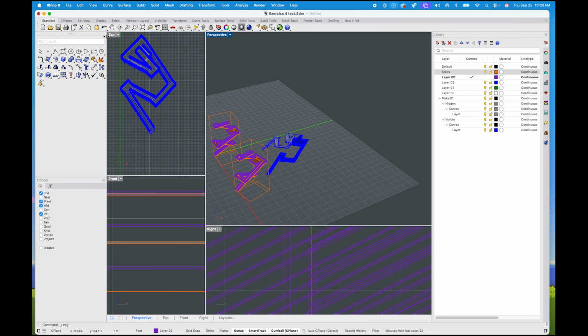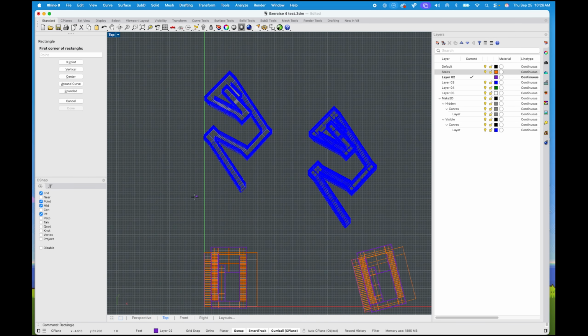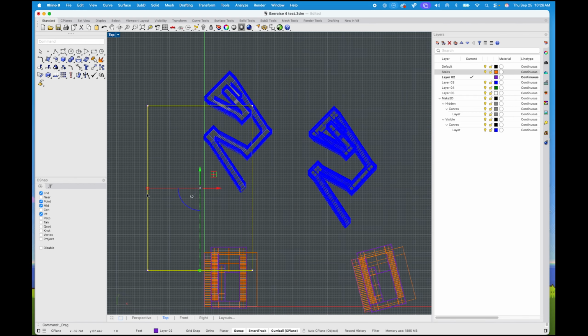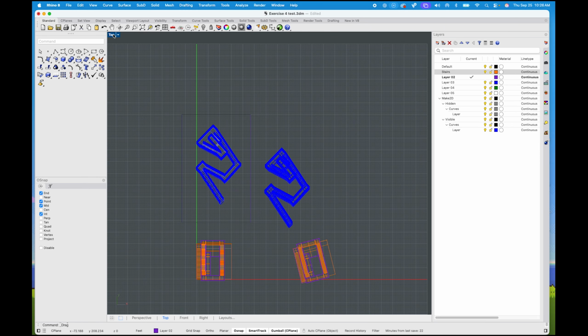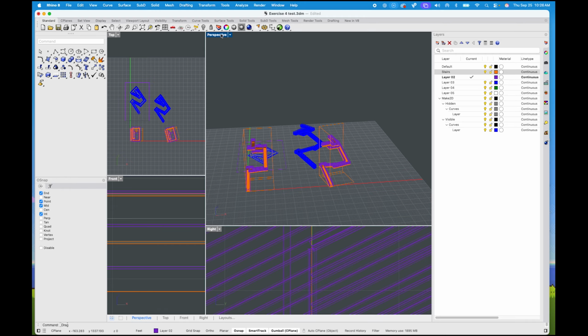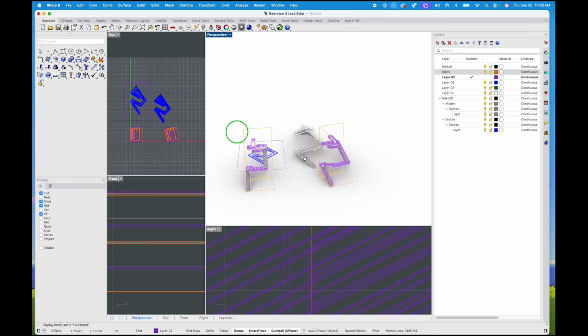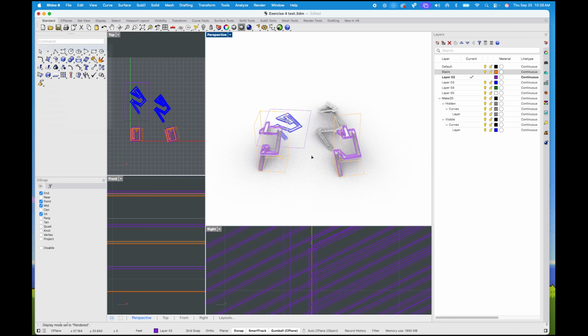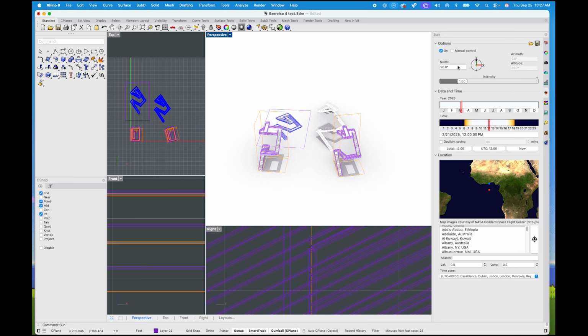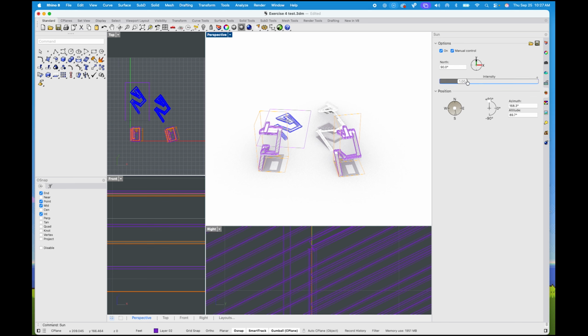So again, from here, I would take that rendered view and my 11 by 17. So in my case, we'll go with 11 feet, enter, by 17 feet, enter. And I'll basically just keep that proportion. Again, not really scaled or anything here. I'll put maybe a nice view of the shade and shadow for those pieces, right? Sorry, let's get some shade and shadow in there. Realistic, rendered view. Let's type in sun. Get some of that sunlight. Make sure that it's on. Right. And let's go with a manual situation. And make sure you get some shade and shadow.